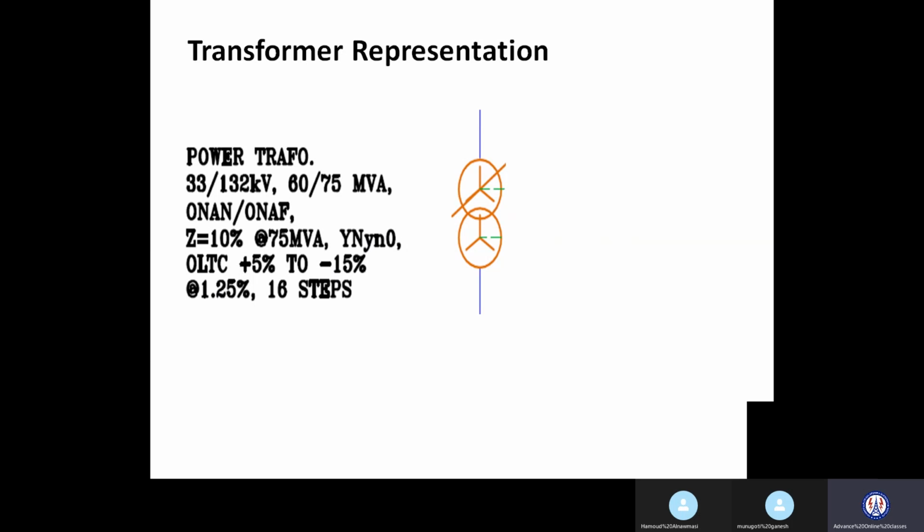Okay. Now OCTC, off circuit tap changer, is always used in small distribution transformers. Those are distribution transformers with rating below 10 MVA. On those transformers we use OCTC, off circuit tap changer. For example, if there is any distribution transformer, you can say utility transformer, and suddenly voltage is low or fluctuates.